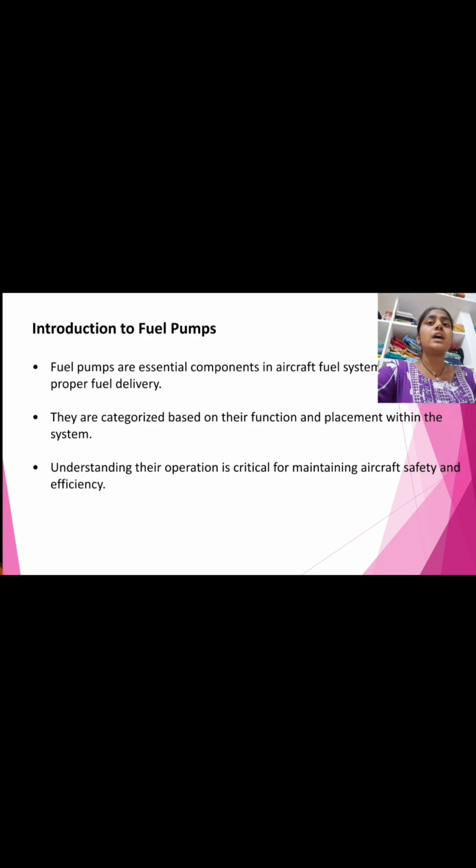Fuel pumps are generally classified into three main types based on their function and operation. They are boost pumps, transfer pumps, and engine driven pumps. Each type plays a specific role in the overall fuel system and operates under different conditions to meet system requirements.